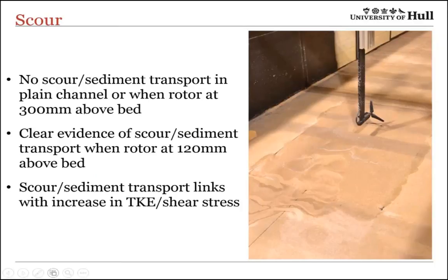What we've also been doing is looking at the effect that this turbulent structure that I've talked about here in detail, and the changes in that vertical momentum exchange with the bed, how that propagates into seafloor scour, which is ultimately what we're going after. So some of the results that we've been getting in terms of how we generate scour with different positions of the rotor above the seafloor, and when it's higher within the flow, as you'd expect, you get less seabed interaction and as a result less scour. But we're trying to constrain that and non-dimensionalize that for future investigations.